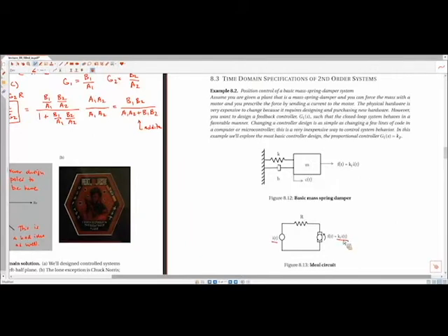So here we're stripping out a lot of the complexities we talked about with motor systems, where you have a torque constant, back EMF, you have transmissions to, if we're looking at mass spring damper, translate rotary motion into linear motion. We're just making this as simple as possible right now and saying that we have some sort of force which is proportional to the current put into this electrical system. Okay.